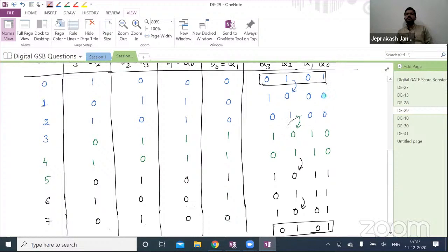Or in other words, whatever counter or sequential circuit is given, that particular sequential circuit will repeat these states. All these states it will repeat. Here it starts from 0, 1, 0, 1, then 1, 0, 0, and like that it changes from one state to another for each and every external clock pulse. After reaching the original state, if you apply further clock pulses, you will get this one, then the next, and the process will continue. That means, for the given circuit or counter, how many different states is it going to repeat? Here also, just count how many different states you have.